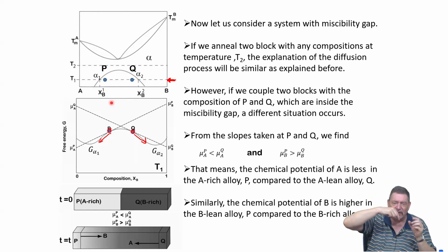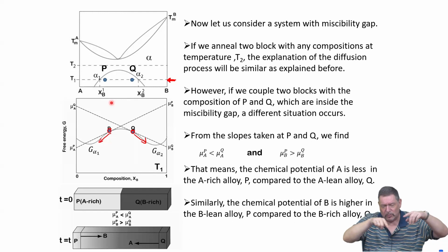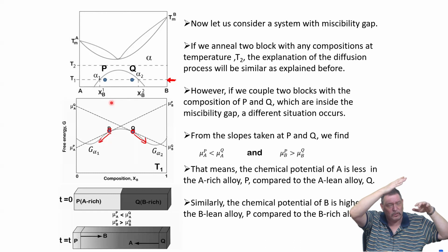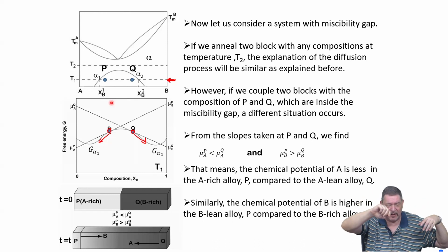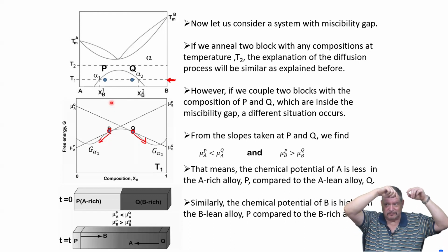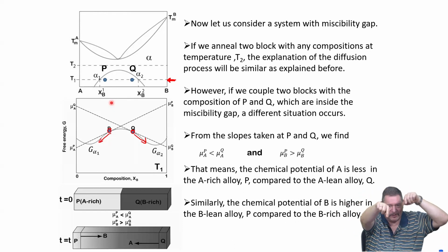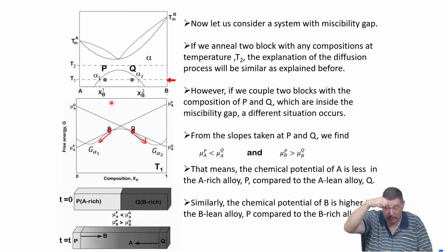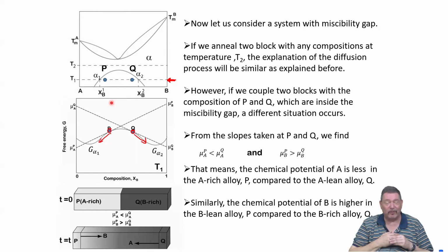And depending on the pairwise interaction enthalpies, you could have different curvatures. You know, between A, B, it could be like this, so it's convex, but there could also be a concave part to element C. And this would give rise to uphill or downhill diffusion depending on where in this triangular energy landscape you are. So it could be very, very complex.